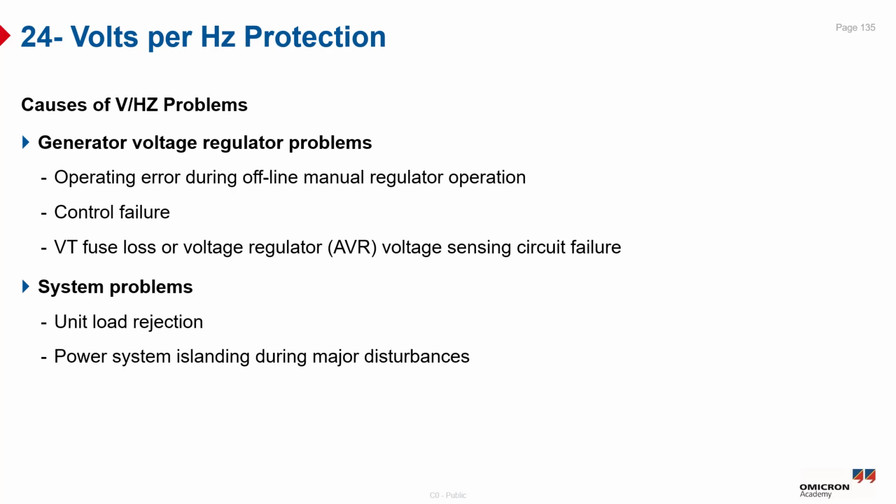Overexcitation occurs when the voltage to frequency ratio exceeds the design limits, saturating the magnetic core and inducing stray flux into non-laminated components. This leakage field, which increases with the voltage and decreases with frequency, can lead to higher losses, overheating, and eddy currents, causing interlaminar voltage that degrades the insulation.